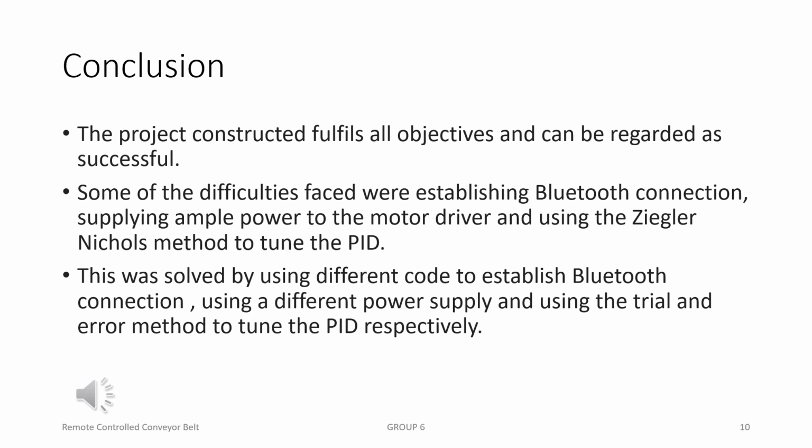At the end of the presentation, we come to our conclusion. The project constructed fulfills all objectives and can be regarded as successful. Some of the difficulties faced were establishing Bluetooth connection, supplying ample power to the motor driver, and using the Ziegler-Nichols method to tune the PID. This was solved by using different codes to establish Bluetooth connection, using a different power supply, and using the trial and error method to tune the PID respectively.